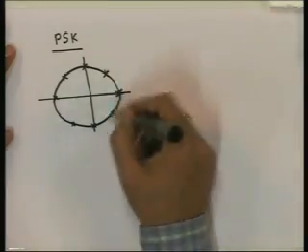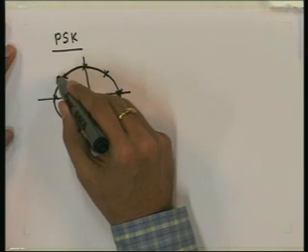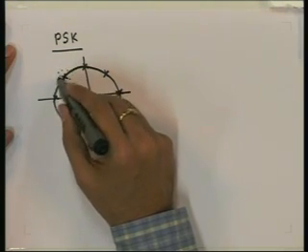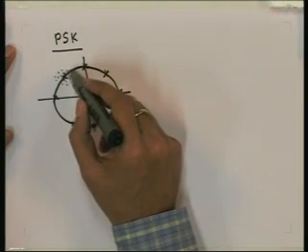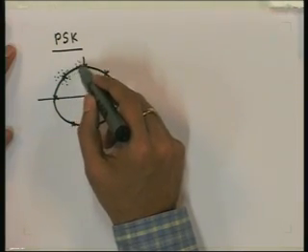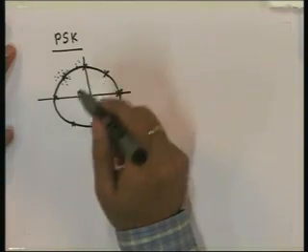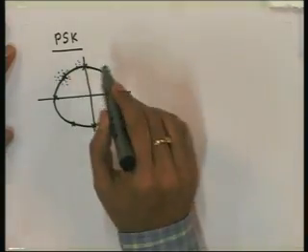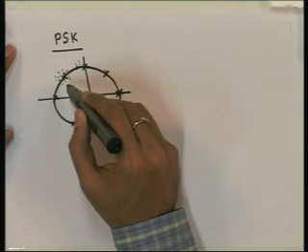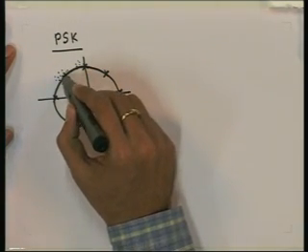Now, when the noise corrupts this signal, if we transmit for example this, we will receive somewhere here, one of these points probably nearby. If the noise is too much at that point of time, then it may go to near here also, then we will decode wrongly because it will come nearer to another point. But anyway, we cannot do anything about that because we cannot remove the noise completely. So, what we need to find out is to select the nearest point in the constellation.